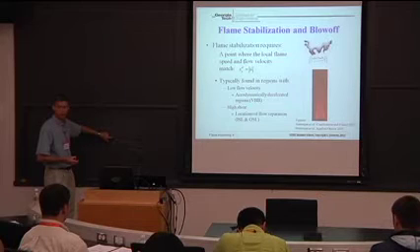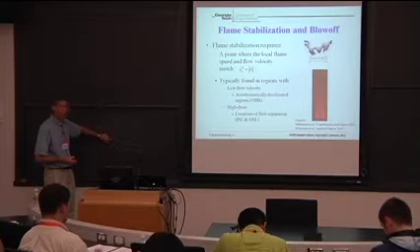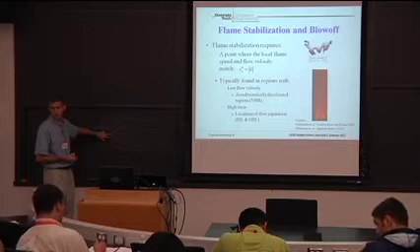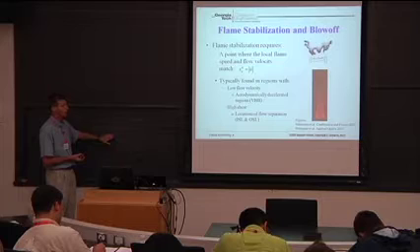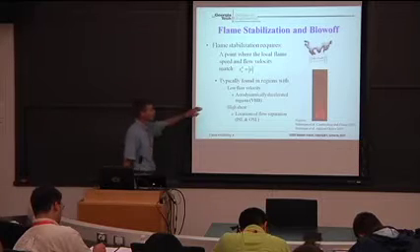If you don't have flashback, you can actually have a stable flame sitting here. And as I told you, the flow at a stagnation point has a low velocity region. So this is a potential flame stabilization point. And there are commercial designs out there which use exactly this principle to hang onto a flame. So that you can have aerodynamic deceleration.